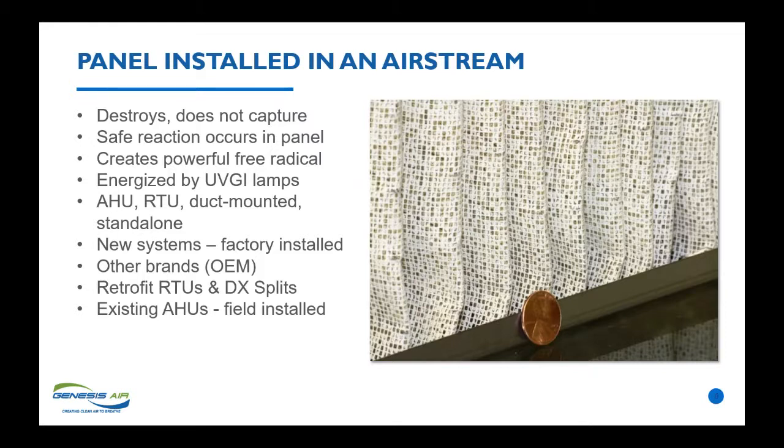So this is not a legacy technology. It's not a filter. The reaction is safe. It only occurs in the panel, not out in the space. It does create a very powerful free radical, the same one we use to clean the atmosphere 7 miles up. It's energized by a UVC germicidal lamp, which means the product itself has a germicidal effect on surfaces within the air handling unit.